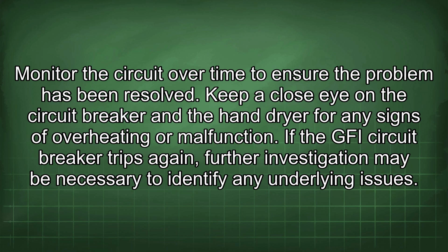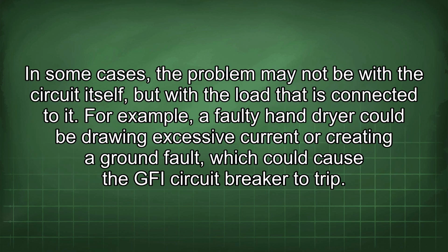Keep a close eye on the circuit breaker and the hand dryer for any signs of overheating or malfunction. If the GFI circuit breaker trips again, further investigation may be necessary to identify any underlying issues. In some cases, the problem may not be with the circuit itself, but with the load that is connected to it. For example, a faulty hand dryer could be drawing excessive current or creating a ground fault, which could cause the GFI circuit breaker to trip.